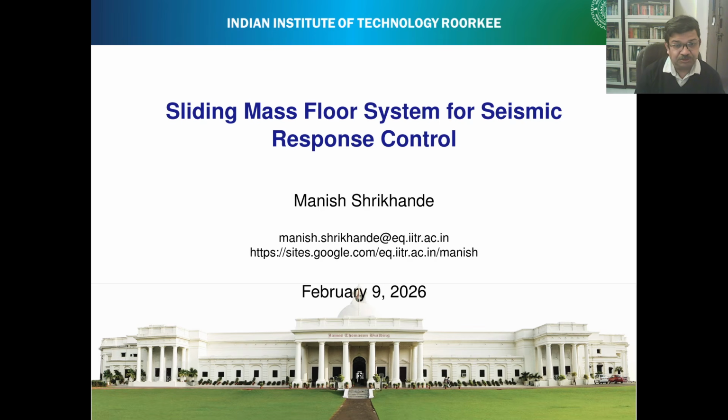important from the point of view that with the recent revision of IS 1893, the seismic demand has increased by several folds at several locations, and existing building stocks are seismic deficient after this current revision, even if they were designed according to the earlier code.